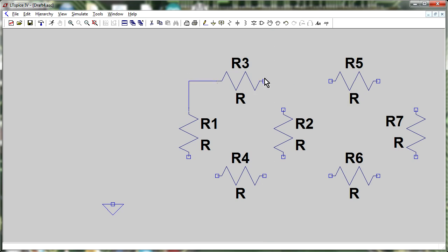You'll notice that little box around the point on the end of the resistor there, that indicates that that node is not connected. So if you see any of those boxes on your schematics at all, then you will know that that point is unconnected. It automatically puts the junctions in there, and it is fairly easy to just draw up your circuit like